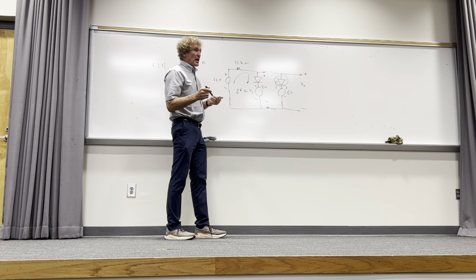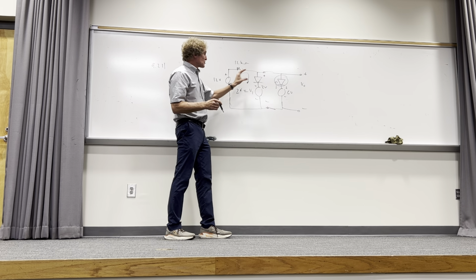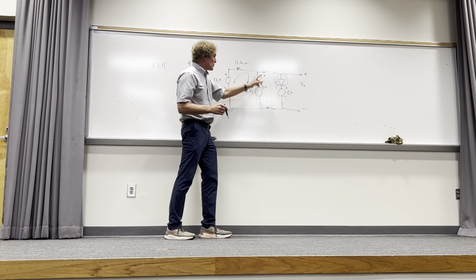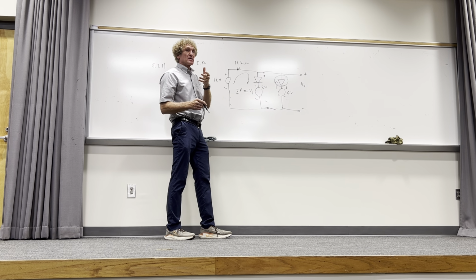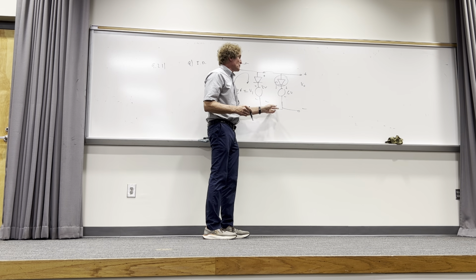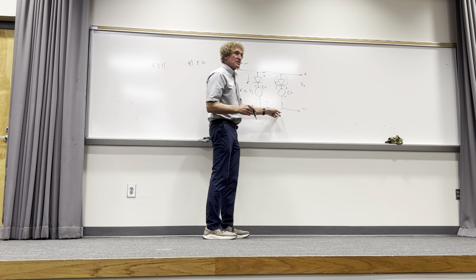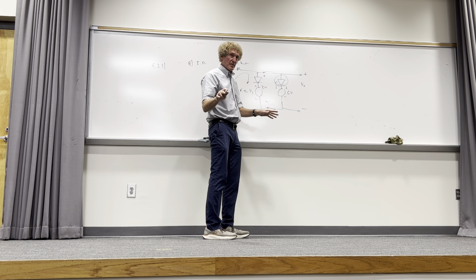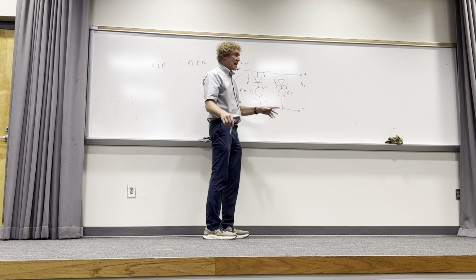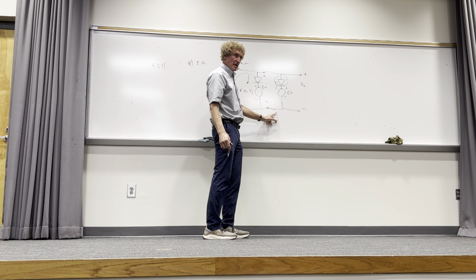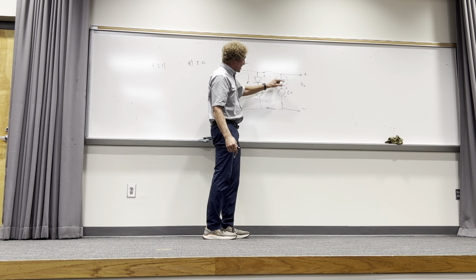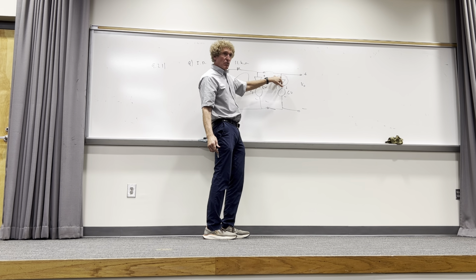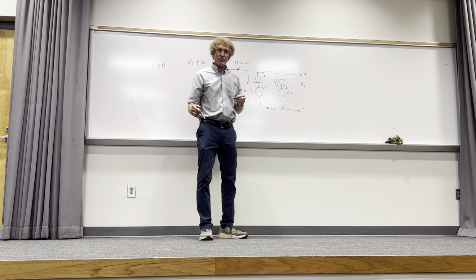So then you go back down and say, well, if this one is on, what happens? I would have 2 volts there. That is a possibility. If I had 2 volts there, would anything flow in this circuit? Zip, right? Y'all with me on that one? It can't. I can have 2 volts here, right? But for current to flow this way, I would have to have greater than 6 volts here. Do y'all follow me, class? I want you to think that through.